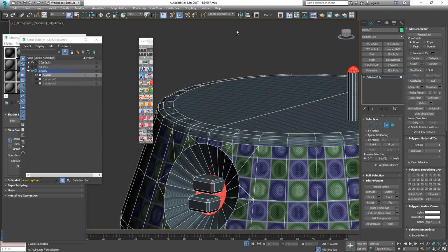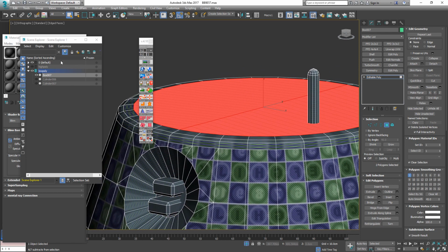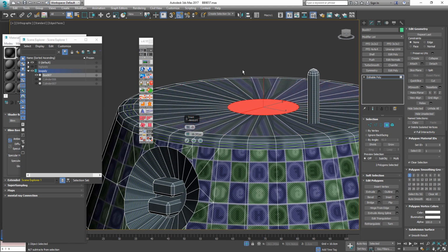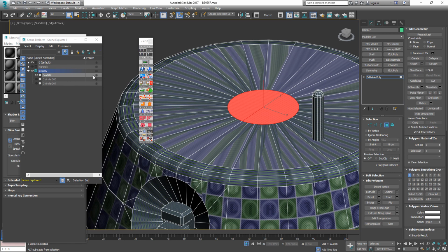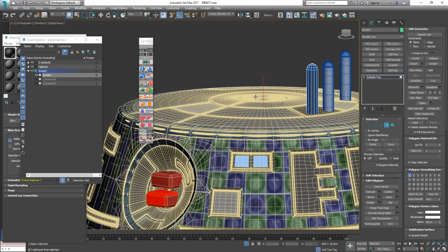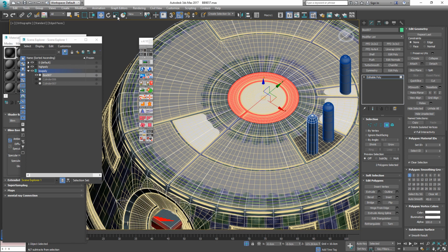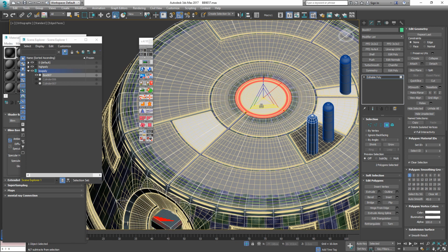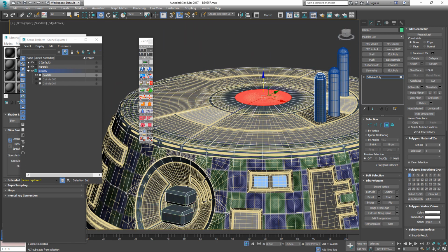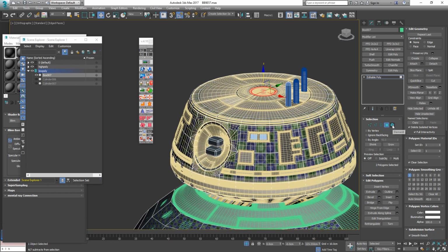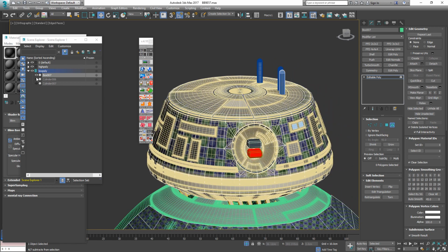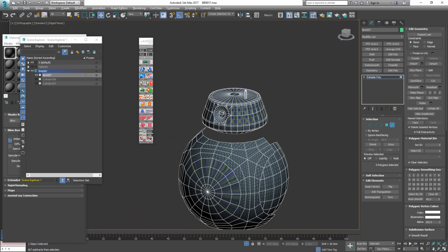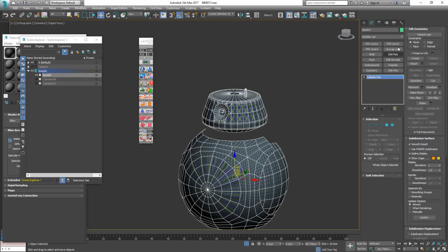If you click on it twice where it says check, let's go back to our low poly here on top of the head of that cylinder. And let's add an inset that we're gonna bring all the way in here. And now let's just re-enable our high poly so that it shows. And we're gonna push that polygon element up here on the low poly so that our low poly also has a little bit of a height there, same as the high poly has it. But otherwise we don't need that many iterations or edge loops. I'm gonna also delete that second light here on the low poly because we can simply share that later and we save some texture space.